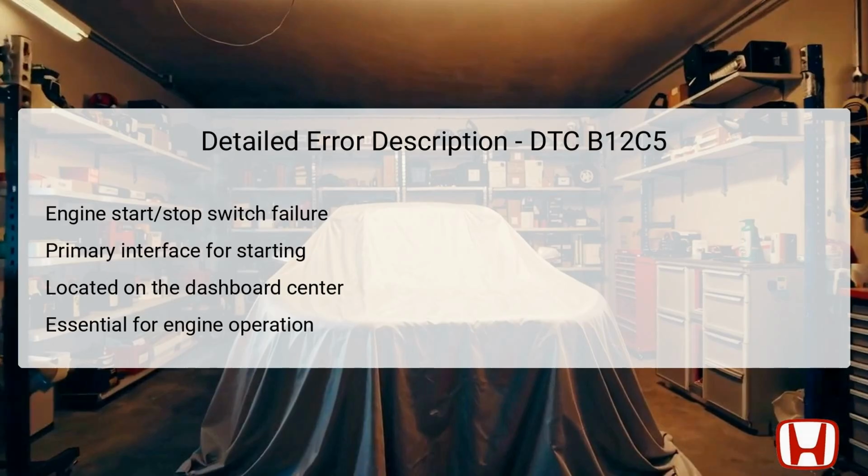Its function is not merely to start the engine, but also to signal the vehicle's electrical systems to engage or disengage based on user commands. When failure occurs, the system may not respond to user input, thus signaling a malfunction. This DTC code indicates that the switch may no longer be sending the correct signals, which necessitates immediate attention. Failure of this switch can lead to starting difficulties or even unintended engine shutdown, which can pose safety risks while the vehicle is in motion.